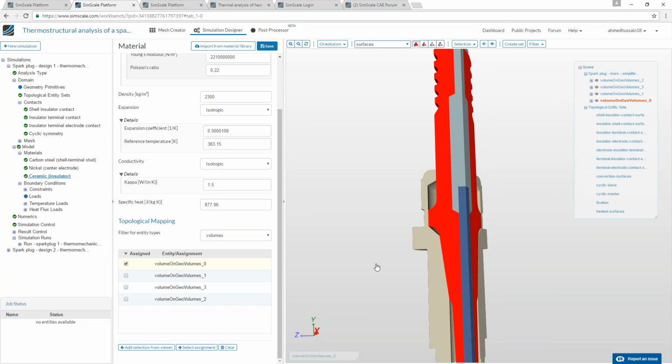So the adaptive mesh, the automatic mesher, meshes according to the domain of the model. It adapts the parameters of the mesh according to the size of your model, the whole geometry, for example the whole assembly. With manual mesh refinement, you can define a global refinement which will be applied to the whole model.